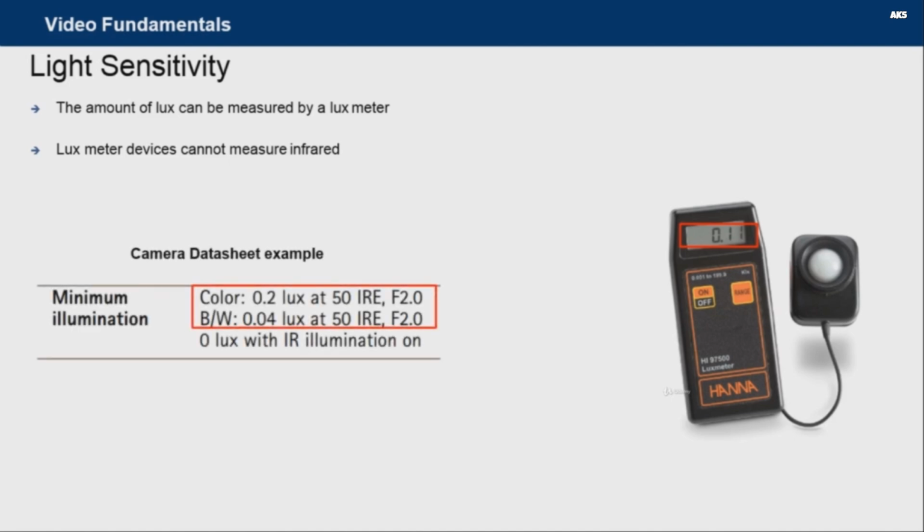The amount of light that is required to produce a good quality image depends on the camera and how sensitive to light it is. Many manufacturers specify the minimum level of illuminance needed for a network camera to produce an acceptable image. A similar comparison between products from different manufacturers is flawed by default. This is because different manufacturers use different methods and have different criteria for what is an acceptable image. In other words, the process of measuring light sensitivity is complicated, and to be honest with you, there are several reasons for this.